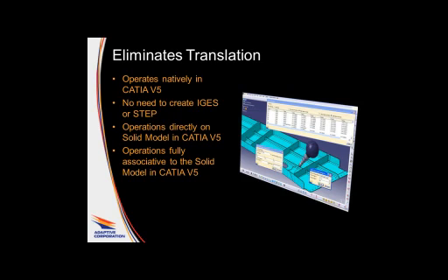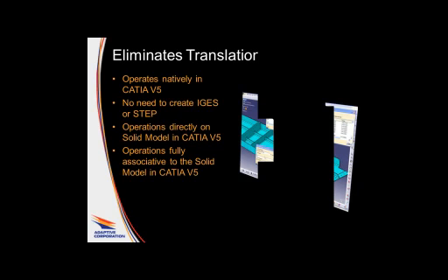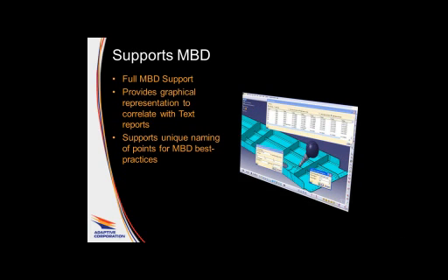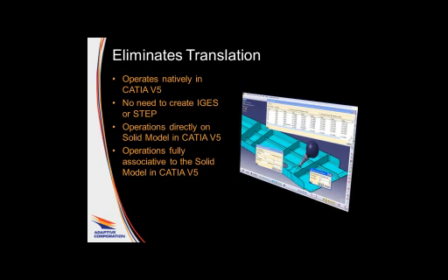We post to most major CMM software. I think we have like 6 different flavors of DMIS that we post to. So most CMM software out there today, we can post native to that. And one of the big things is we do not tie up the CMM during the programming process. The goal is to have a CMM program ready to run when the part is manufactured. So your CMM programmer is not down on the machine tying up the CMM. Our goal is that the CMM should be running and programs should be made offline. Next slide, please.